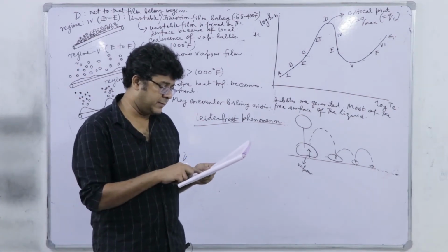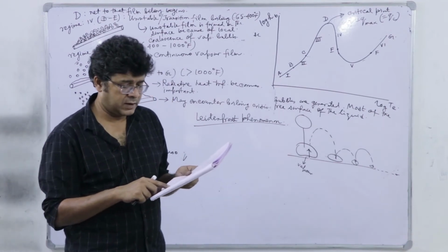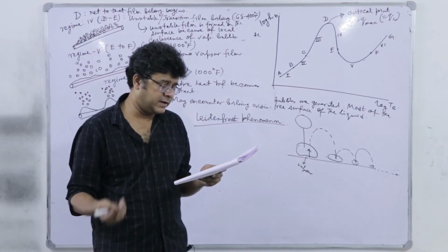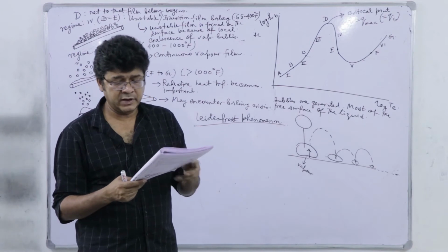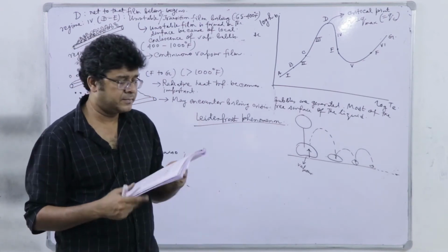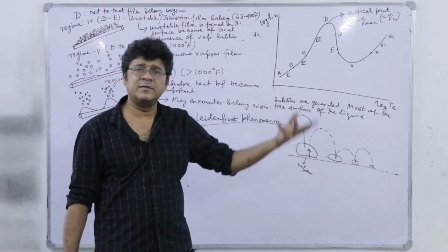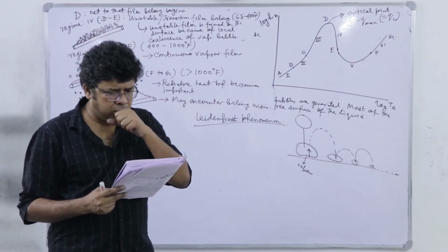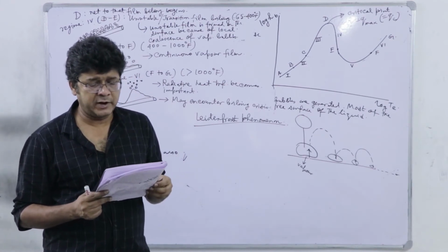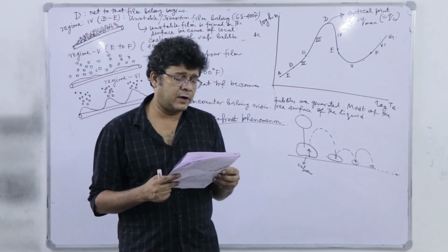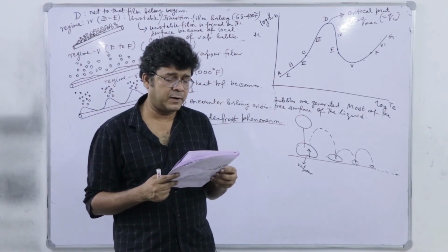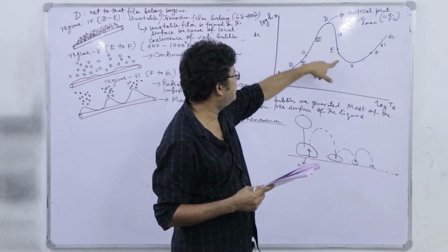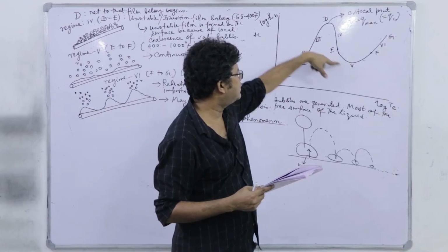So, when a water droplet lands on a hot surface, a film of steam immediately forms between the droplet and the hot surface, and because the thickness of the vapor film increases very quickly by further evaporation of the liquid, the droplet experiences an upward thrust and it again falls back because the film is getting released. So, this is called the Leidenfrost phenomena. Leidenfrost phenomena is caused by film boiling and occurs for evaporating droplets on a hot surface corresponding to this regime, that is a stable film boiling here, right, this regime 5.